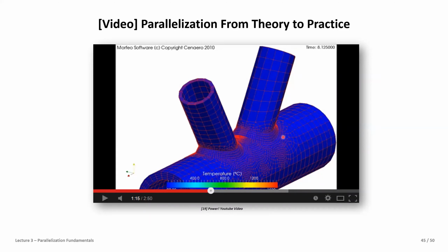If you look at the video, you will see the domain decomposition is much more fine-grained here, because here is where all the stress is, where the physics has a hard time to compute, while the outer parts are more or less constant or just not moving that much. The main concentration on the material is here, and hence the domain decomposition is much more fine-grained here to compute more accurately and speed up the computation, especially in these areas.